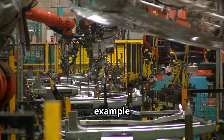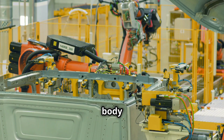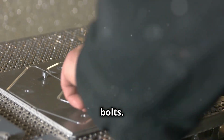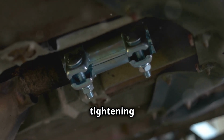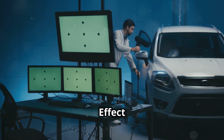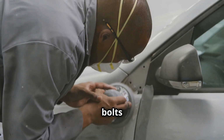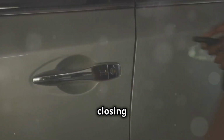Let's look at a simplified example in an automotive assembly line, where a critical process involves attaching car doors to the body of the vehicle. Step 1. Process step. Attaching car doors to the car body using bolts. Step 2. Potential failure mode. Improper bolt tightening. Bolts are either too loose or too tight. Step 3. Effect of failure. Loose bolts could lead to doors rattling or falling off, causing a safety hazard. Over-tightened bolts could damage the bolt threads, leading to door misalignment or difficulty in opening and closing the doors.